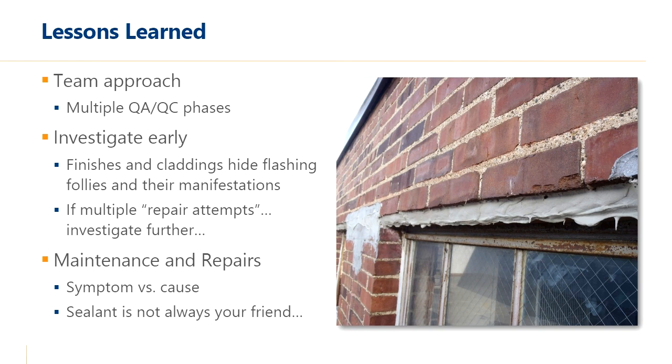Besides that overall team approach, I hope it comes across how important it is to investigate these systems early. Flashings and claddings really hide deterioration within them. But one good rule of thumb that I would recommend is if multiple repairs have been attempted and they haven't addressed the issue, that's when it's maybe beneficial to bring in somebody to investigate it further, because maybe just the symptoms are being addressed and not the cause.